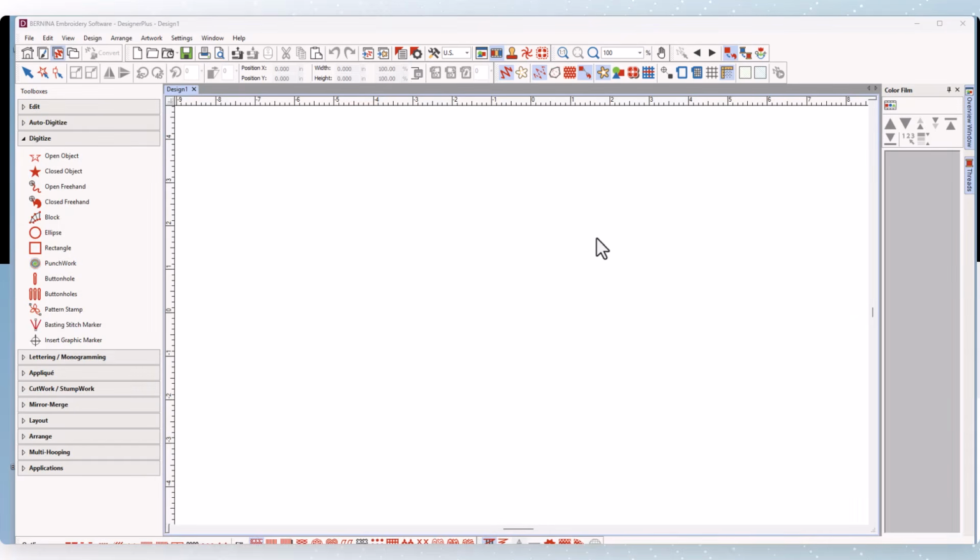You have three options when you bring in a stitch from the machine to the software. First of all, your pattern stitches can be created from a grade C or grade D stitch file. Pattern stitches can also be converted to a grade A stitch file by digitizing over the pattern. Or the third option is pattern stitches can be converted to grade A using artwork canvas to convert them to artwork, and then you convert them back to stitches. You'll learn about each of these different ways.